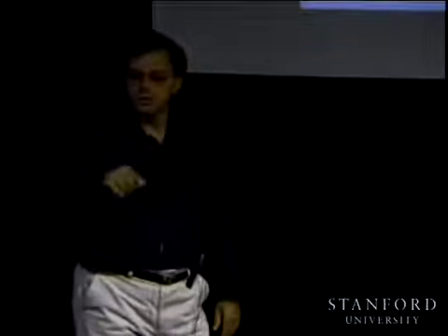And smoothness, you want the manipulator to have a smooth motion because that uses much less energy and it's easier to control. So these are the type of constraints that will be into the problem. Okay, so that's the setup for pretty much everything that we'll be discussing today. Initial point, goal point, intermediate points, constraints, and we're going to be charting the time history. From a mathematical point of view, it's a very simple problem, right? We're planning path.